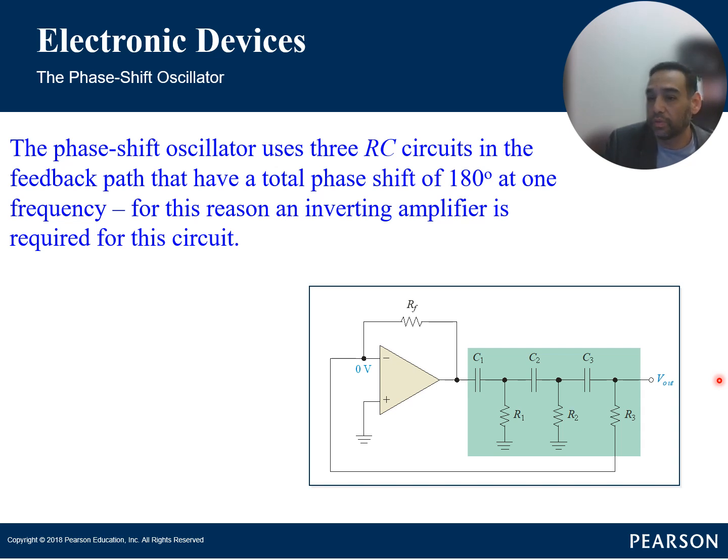So that phase shift, the next factor for the oscillator, across each RC stage, is frequency dependent. So at the oscillation frequency, the combined phase shift around the total loop is 360 degrees, right? So that's the condition required for positive feedback if you have an oscillating circuit in this case.